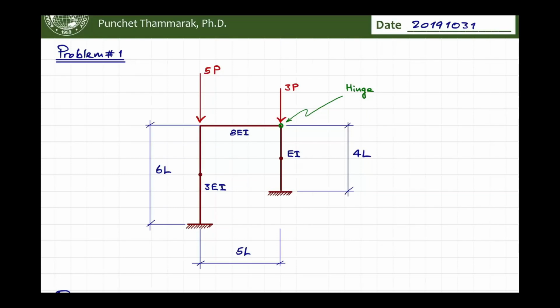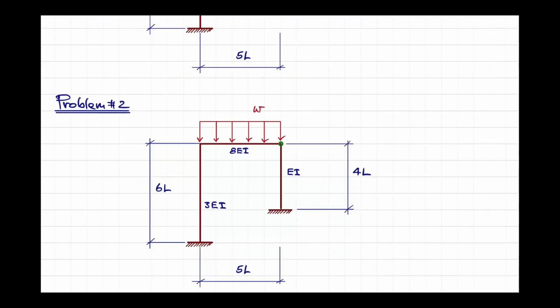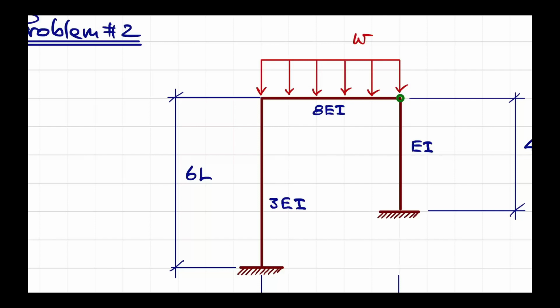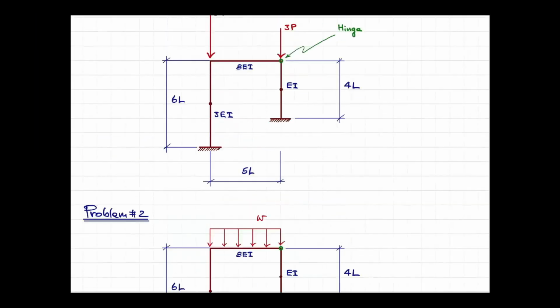Generally the beam is larger in the EI value, so stability will not be the case. Well, for the tall building, the EI for the column will be large in comparison with the beam anyway. But for a typical low-rise short building, we get a very large EI for a beam compared to the column.